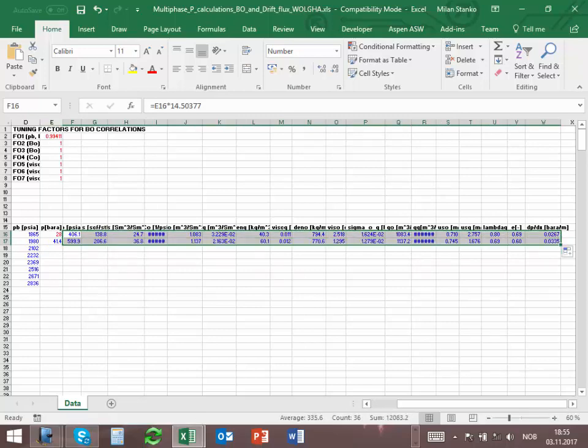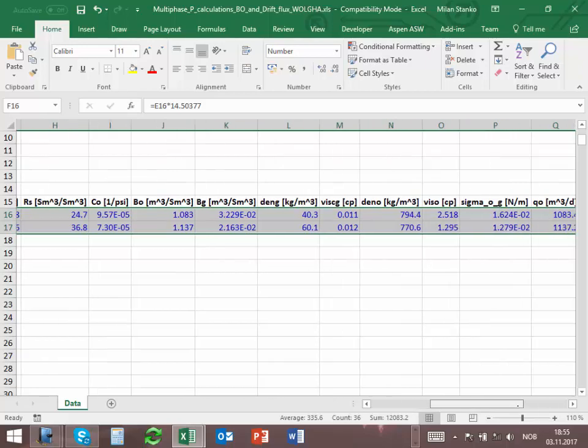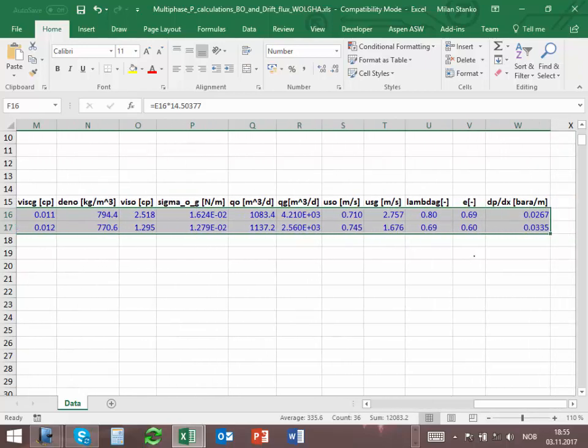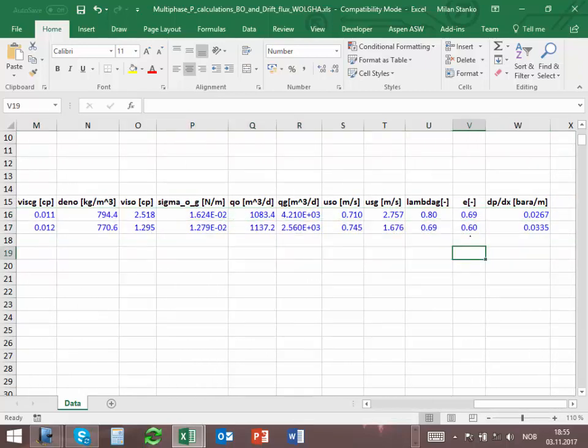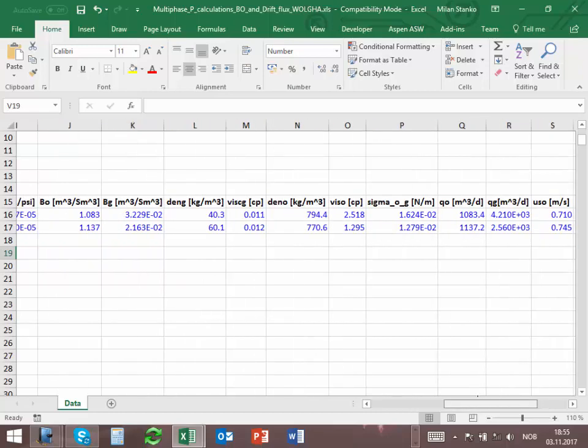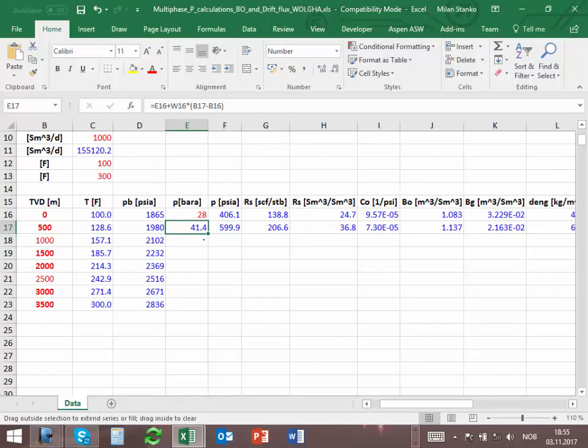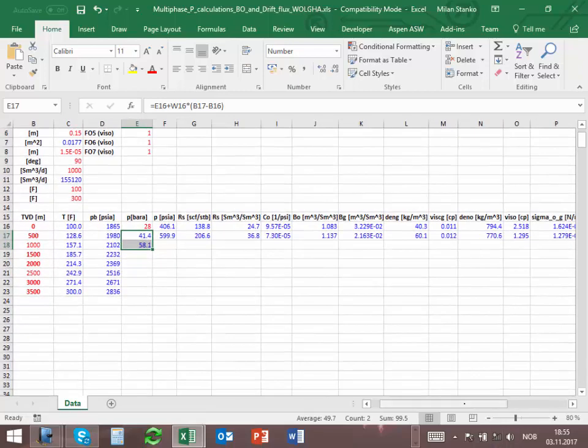And let's look a bit. So what does it mean here? I have now not 70% but 60% of the cross section of the pipe occupied by gas. That means maybe I have less gas. Some of the gas is in solution in the liquid. And because I have more liquid, the pressure drop is higher. It's not 2, but it's 3. Then I can just drag this down, and I move just like that.